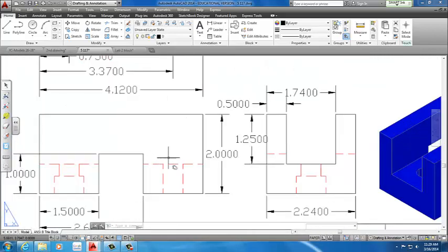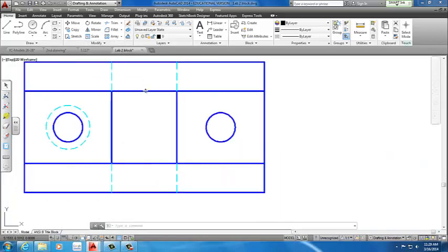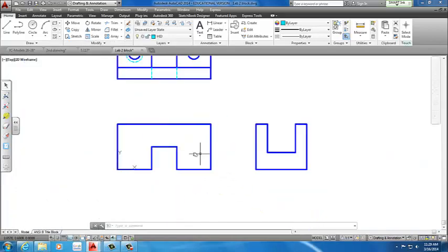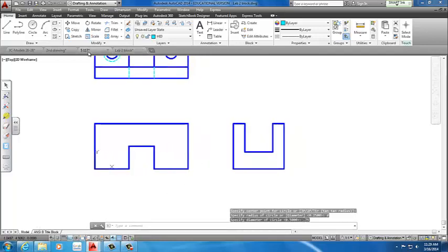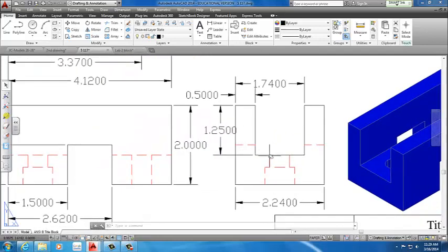What we want to do is create this segmented right side line first. It's easiest, so we'll start there. You can see each part is separate into one single line. To do that, we need to use the polyline edit command, which is called P-edit for short. That is going across. This is the hidden line.